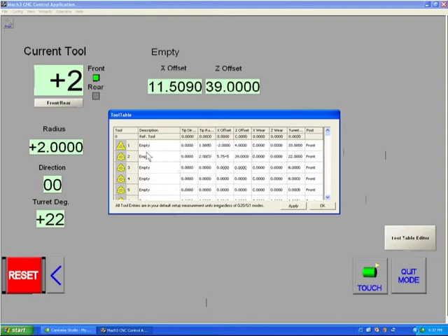entered will be wrong. You can, for the sake of convenience, change your icons to make them look like your particular cutting tool types look. You have a tip direction, a tip radius. These two values are used in tooltip compensation, which will be a separate video. It is an advanced feature of lathes, and it allows you to cut profiles without worrying about which direction your tip faces and so on, messing up the job. The information in tooltip direction and tooltip radius are important to the program so that it knows how to correctly offset the distances that it's moving in a G-code program to compensate for that tool's direction and where it's pointing.